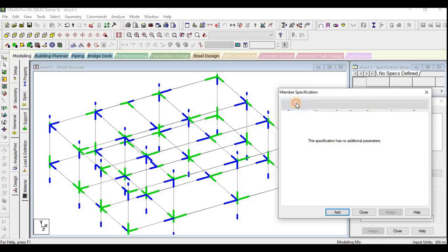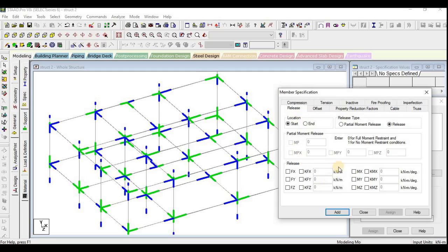In this project we are going to use the release. Here I shall take the top view. Before that I shall explain how the moment is released. Here I have modeled this secondary beam in the x direction. When I have modeled this in the x direction, I need to release in the Z direction. Here there will not be any force transferred, so there will not be any release in the force.